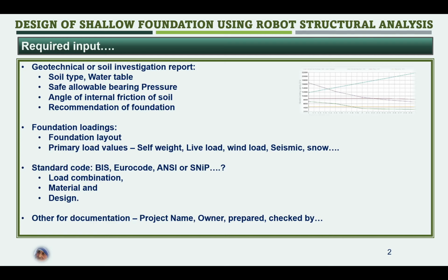Next is foundation loadings. For that, the foundation layout is required to identify which kind of foundation is to be provided. Either it is a single isolated footing which is holding one column, or a combined foundation which is holding two columns in a single base slab.